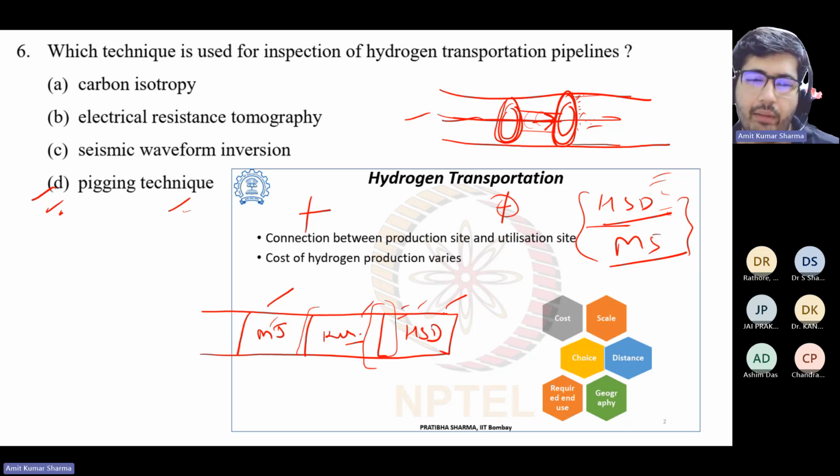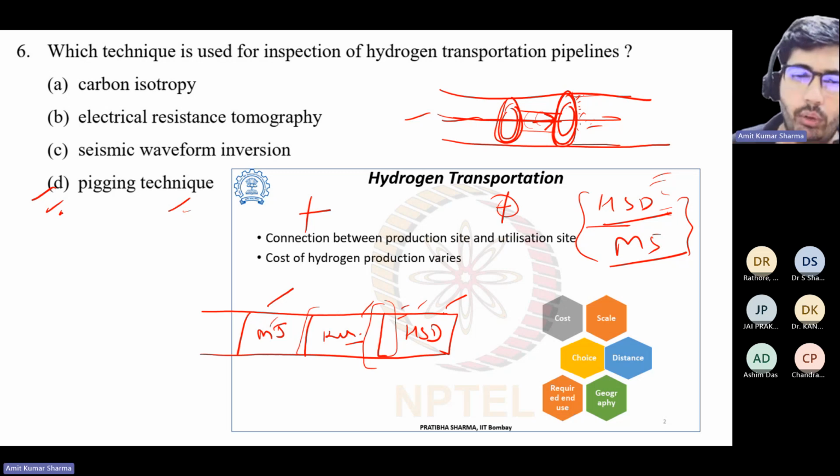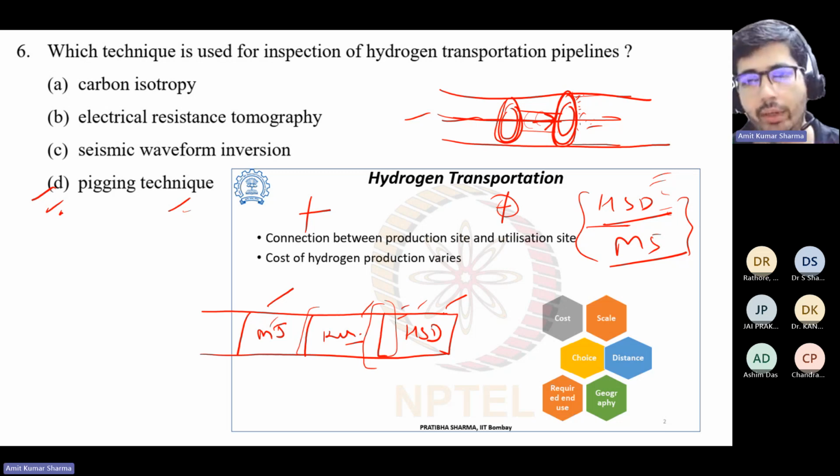At the receiving point you will have an online density meter and everything, and also you will measure manually. You will have sample points, so you frequently measure the density, and because the mix will be there, the density will start changing.